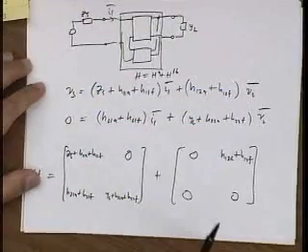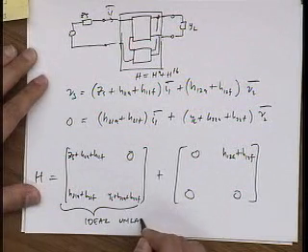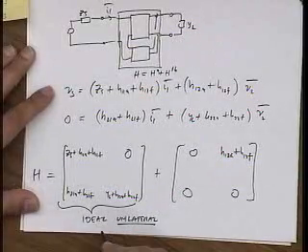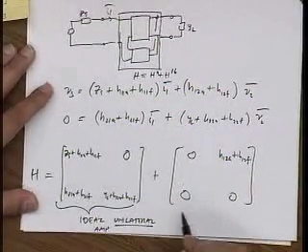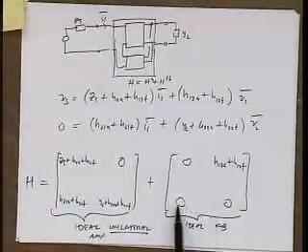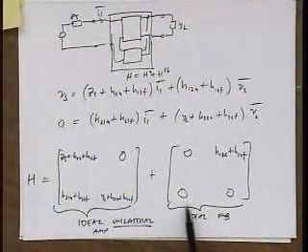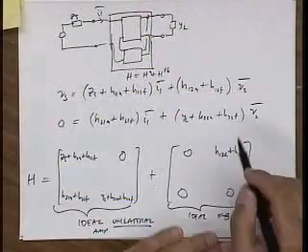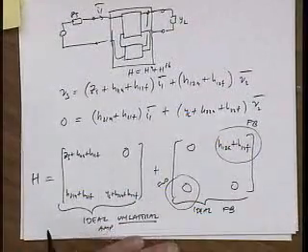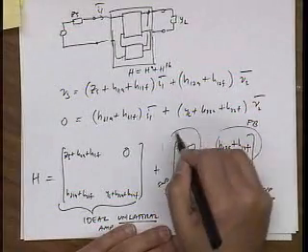Yeah, it's basically very simple. This is an ideal amplifier now. It's an ideal unilateral amplifier. Well, it's maybe not ideal. It has input and output impedance, but it's unilateral. And this is ideal feedback. It's ideal because you notice it doesn't load the input and output at all. It has no forward transmission, right? It just has feedback. So this is my feedback term. This is my forward term, which is 0. And these are the loading terms. So this is the output loading. And this is the input load.